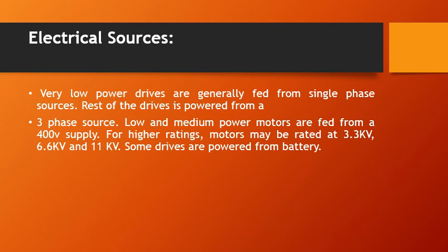Electrical sources. In India, single phase and three phase AC supplies are readily available in most locations. Very low power drives are generally fed from single phase sources, and the rest of the drives are powered from three phase sources, except in the case of traction drives, where even at very high power levels single phase power supply is used because of economy.